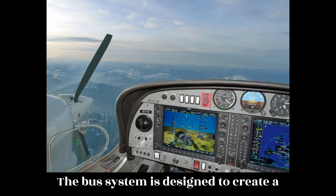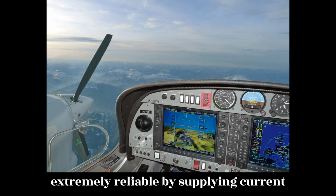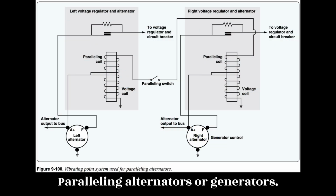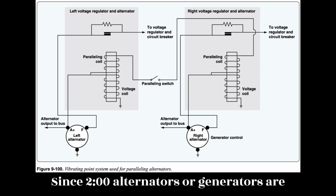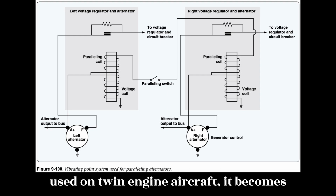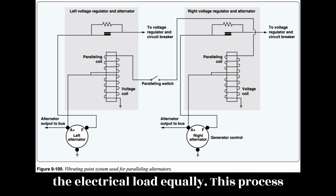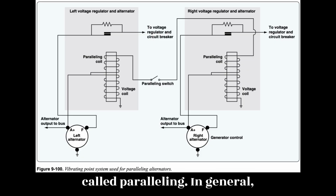The bus system is designed to create a power distribution system that is extremely reliable by supplying current to most loads through more than one source. Paralleling alternators or generators. Since two alternators, or generators, are used on twin-engine aircraft, it becomes vital to ensure both alternators share the electrical load equally. This process of equalizing alternator outputs is often called paralleling.